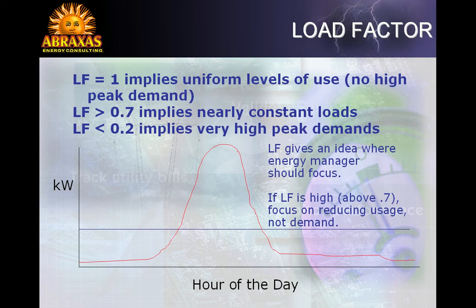If presented with a high load factor, as shown by the horizontal line on the graph of demand during the course of a day, focus on reducing usage, not demand. An energy manager confronted with a low load factor, which would be associated with the bell-shaped demand curve, would want to focus on reducing peak demand.